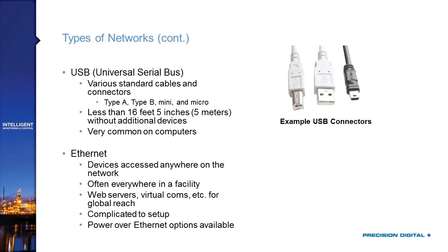But USB, when it comes to Modbus, is really only used for directly connecting a laptop or some kind of programming device. It's used a lot on devices that are going to get programmed on the bench and then installed in the field, because USB is a very short-range system. It's really only designed to go about 16 feet. It's very common on computers, though, so if you are just looking to connect directly to a Modbus device for programming, then USB is probably fine.